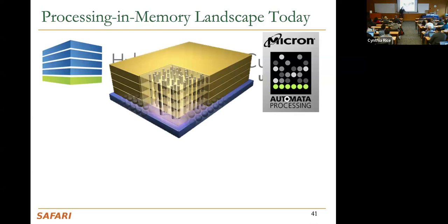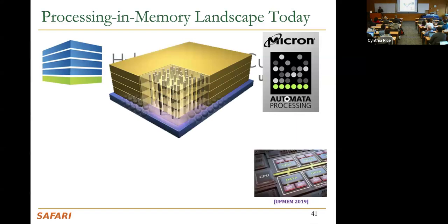People are experimenting with DRAM chips. But compared to 8 years ago, more recently, people have actually been modifying the DRAM chips to put processing in them. This is a startup in France called UpMem. They basically have DRAM chips where, inside the DRAM chip, next to each bank, you have a general purpose processor. So you don't need to move the data outside the DRAM chip. And we've been experimenting a lot with their chips. We show that actually this is useful for some applications.